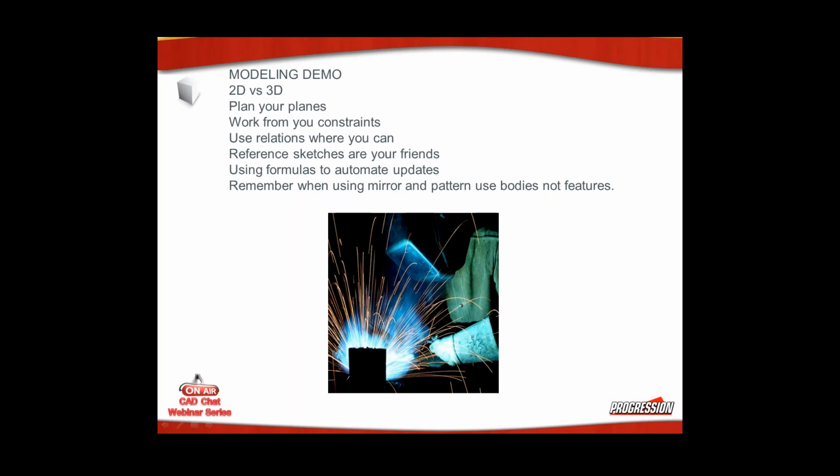Reference sketches are your friends. Don't be afraid to throw an extra sketch in there to drive off of. We all know the value of formulas. Take a little time to figure out where you can use formulas, drive that automation through your model. And finally, mirrors and patterns are your best friends. And when you're in a weldment, remember you're going to be mirroring bodies, not features.